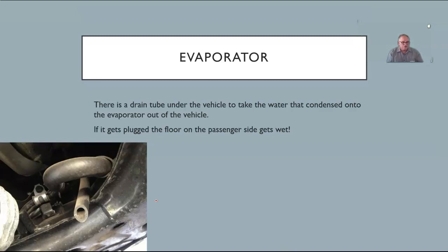And the first thing I do to find out if it's plugged, I take an air hose and blast the air up through there. So just give a shot of air up inside there, and the junk that's plugging it up will be lifted up out of the way, and then some water will run out, and now I know it needs to be cleaned out.